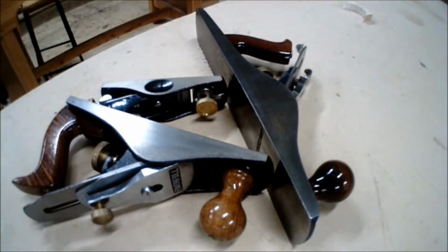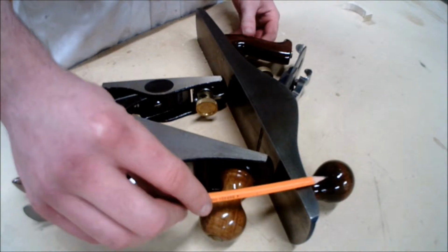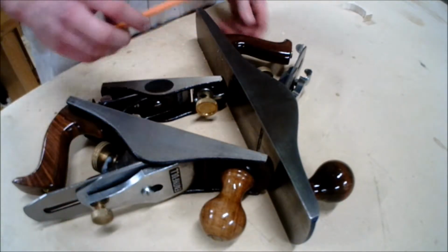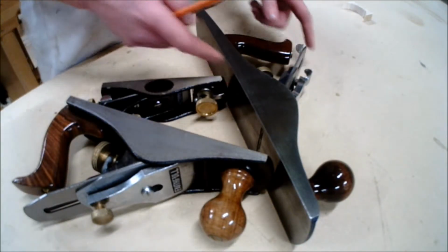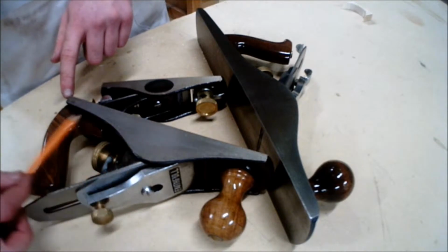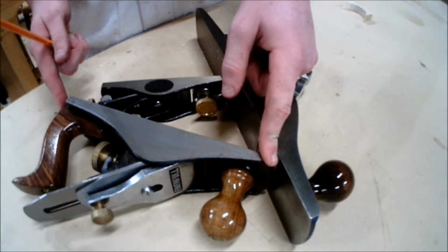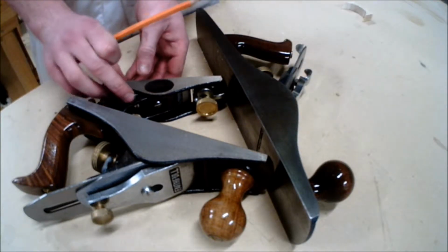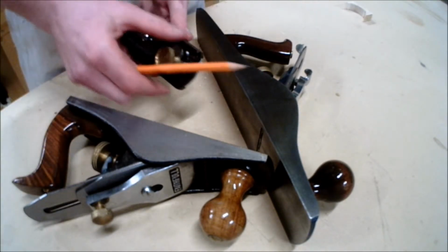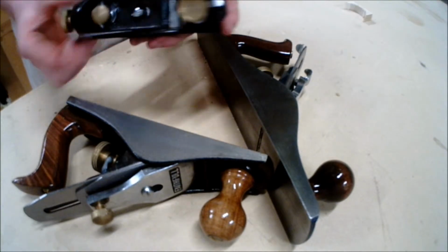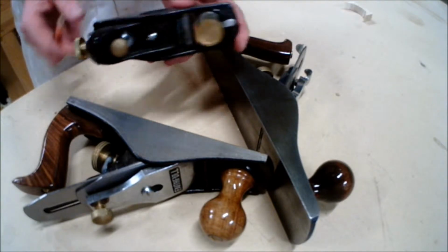There are three main planes that are most commonly used in the woodwork classroom. We have the jack plane, which is a size of 355mm to 380mm and most commonly used on precision sawn material. We have the smoothing plane, which has a length between 240mm to 260mm, most commonly used when finishing flat surfaces. And finally, the block plane, which has a distance of 140mm to 205mm. This is used for trimming end grain and has a small blade width of 42mm.